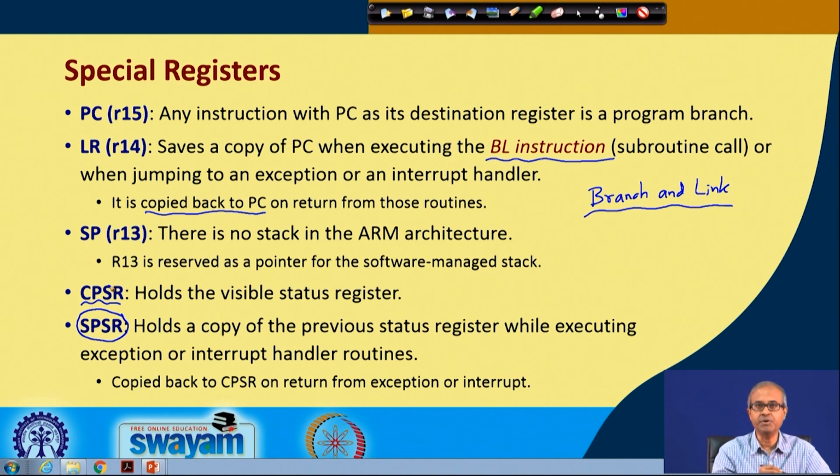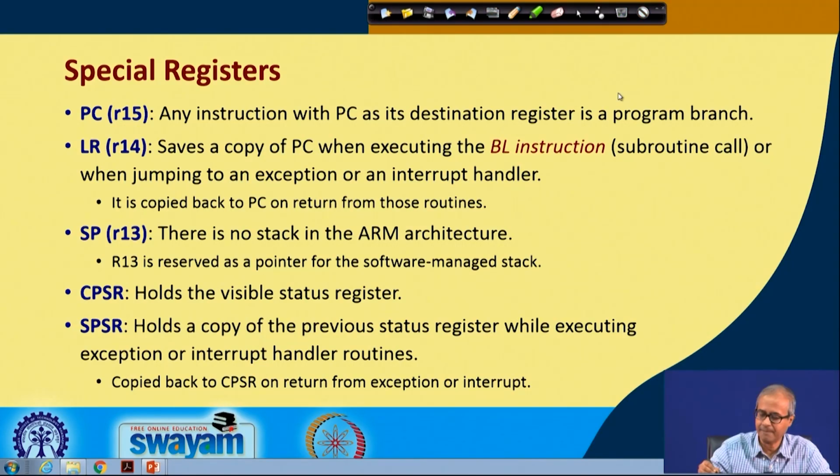They will hold a copy of the CPSR. So, when you come back from the exception routine, that SPSR has to be copied back into CPSR before you resume execution. Okay? This is how they work.